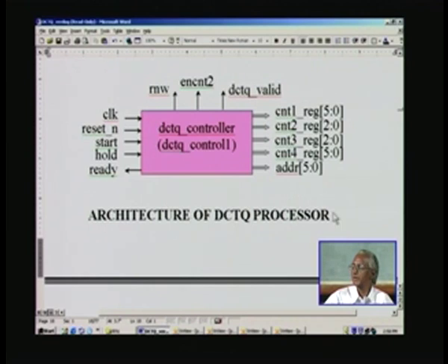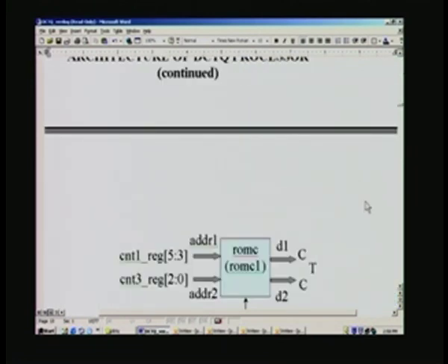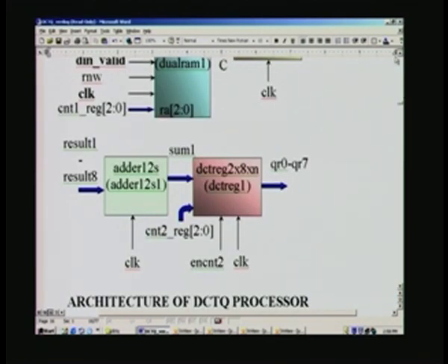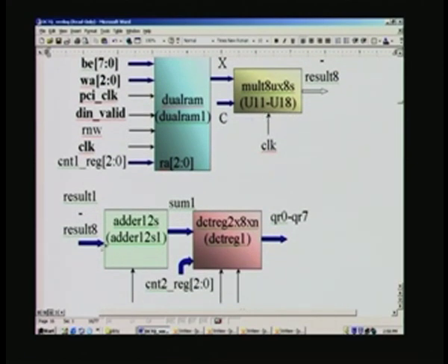So, this completes the architecture, and before this we will once again examine how much delays are involved. Here we saw the 2 pipeline here, 8 here, then you just add all that, 10 here, then 5 here, 15, then 8 here, 23.